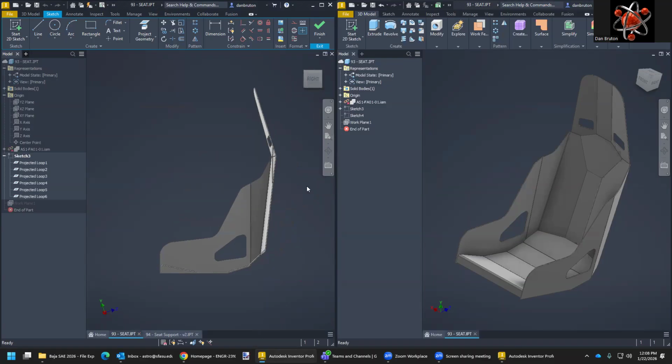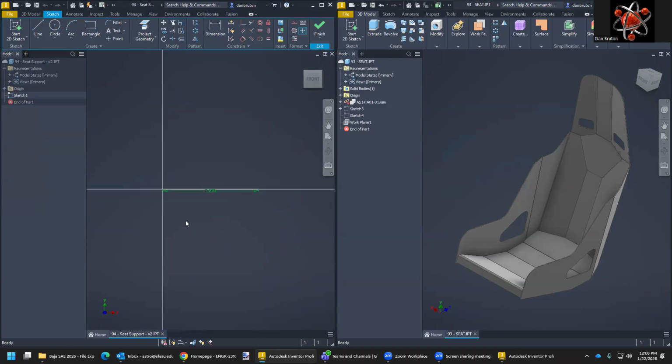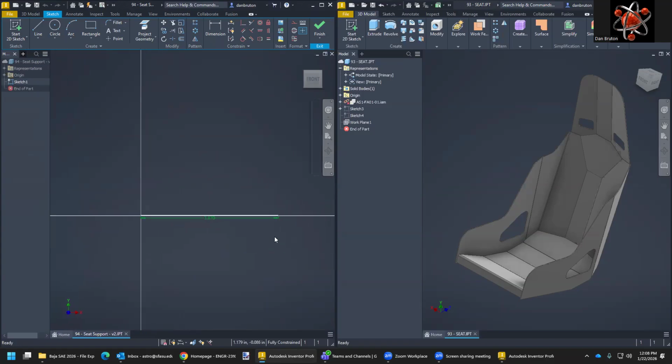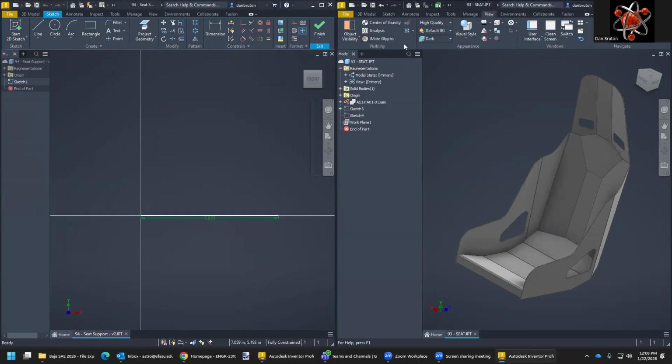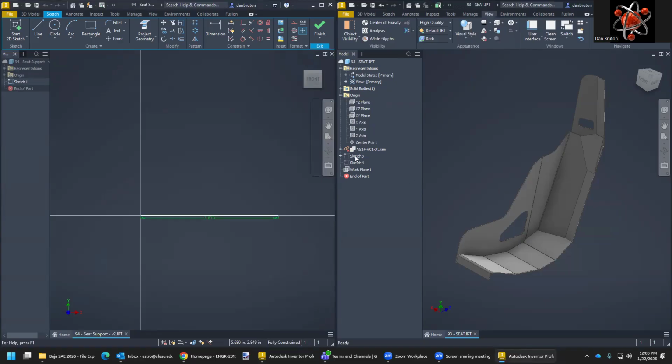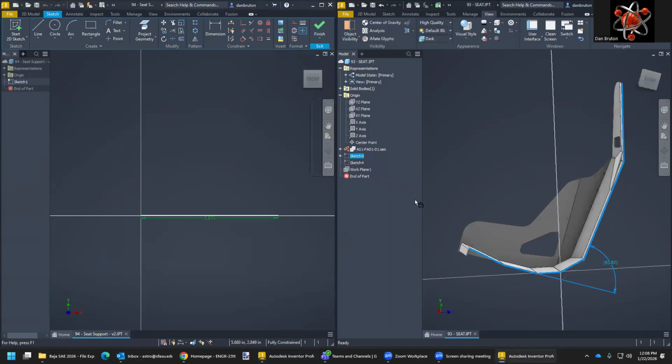Don't save that one, because, oh yeah, I guess I should have. But that's okay. We just need to get these measurements. Remember, you want to go to view and then, looks like it's hidden half section view like this. And we'll select the origin XY plane, cuts it in half, green check mark, and go over here to sketch number 2, edit that sketch. It's going to face it.